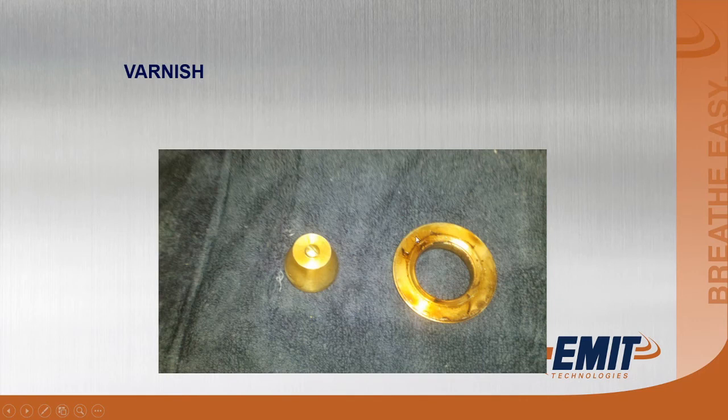When you see jets and valves that are covered in this varnish, it usually means the rest of the carburetor is going to be very sticky as well. You want to keep that from happening. This is just simply gas that's doing this. It's deposits from the fuel gas that they have.